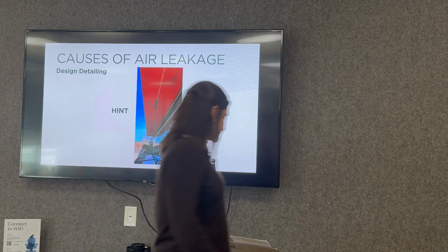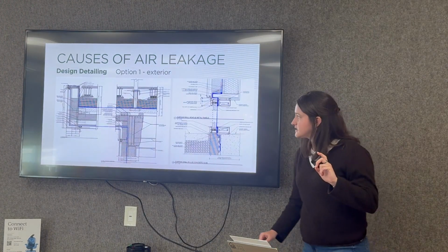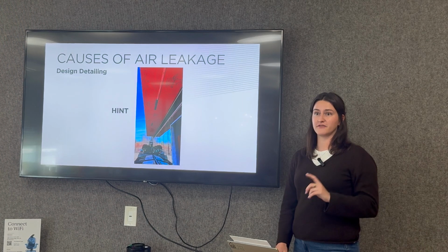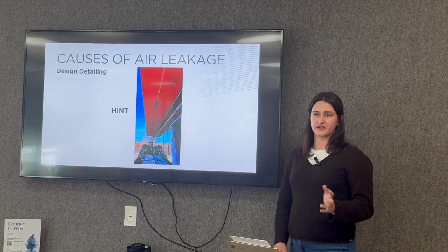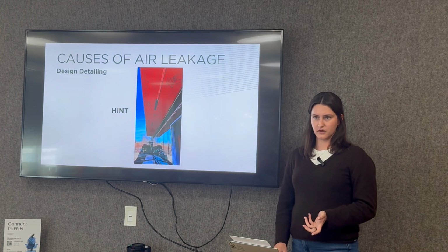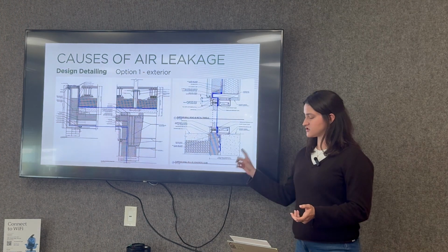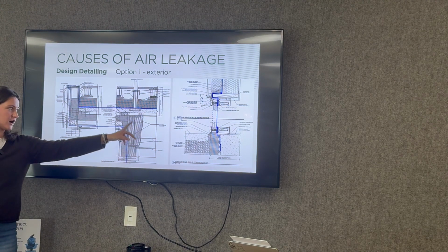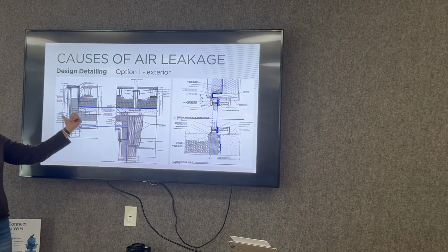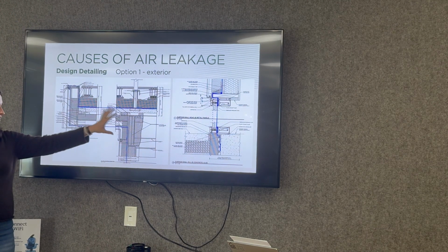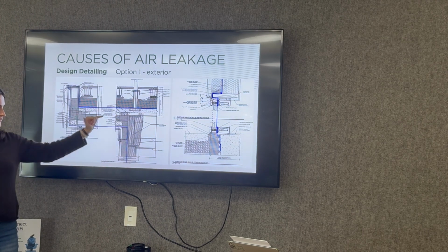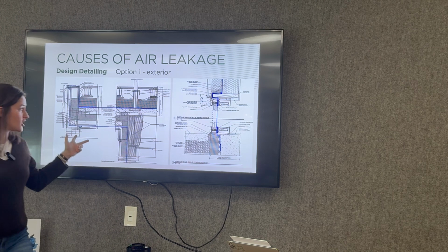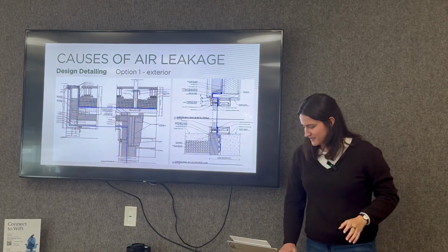So right where this could be detrimental in terms of this detailing is that here we have exterior light fixtures in the soffit. So even if we air seal around every single light fixture, most light fixtures themselves aren't intended to be airtight. So with this as it's installed, in a really cold climate, you're really warm inside and then you're cold outside, which drives the hot air this way, and then you get risk of condensation forming on these two surfaces. And if it's hot outside and cold inside, then you're essentially sending hot air in through your light fixtures up to the inside, which is decreasing the efficiency of your building mechanical systems. So fully on the outside is not the most practical, and doesn't look great.